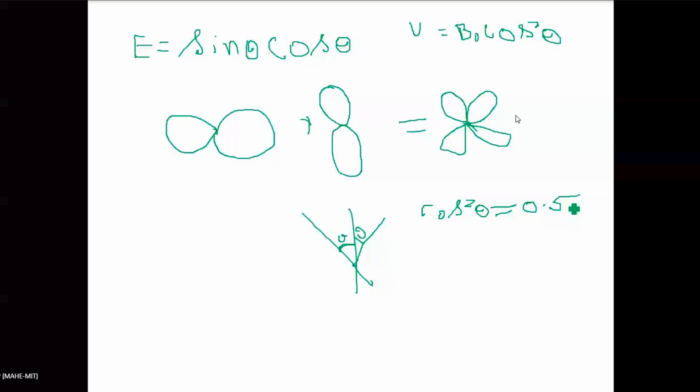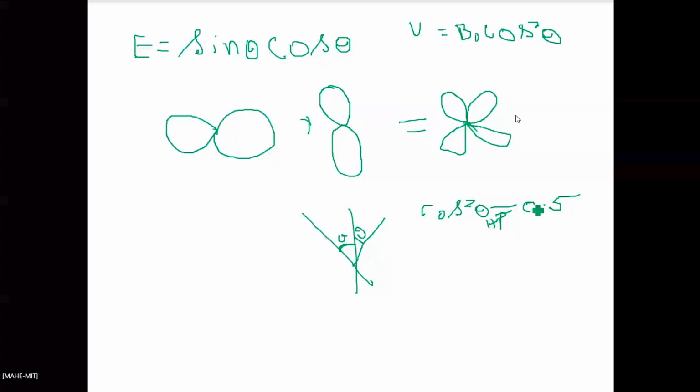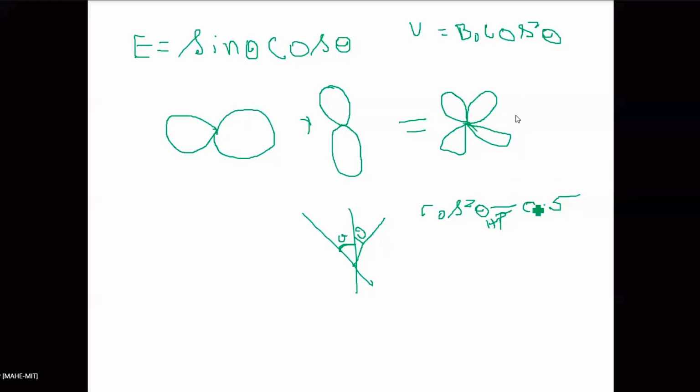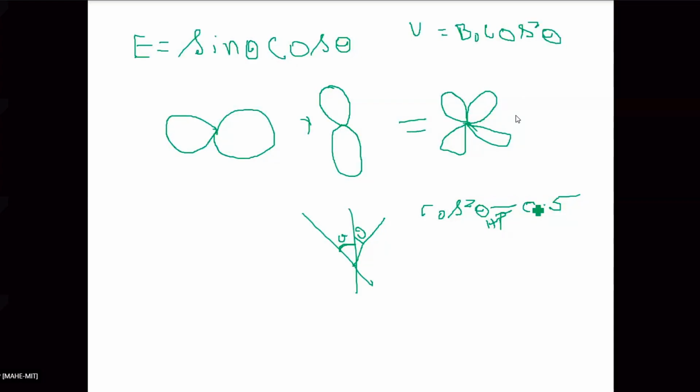So U represents power. I told you, E square or power. If instead of an electric field or amplitude pattern you have a power pattern, with U given as B naught cos squared theta, then the half power point is found from cos squared theta equal to 0.5. Then you find theta hp and the half power beam width. You should not make the mistake of substituting 0.707 for cos squared theta hp. Only when an amplitude pattern is given can you substitute 0.707. When a power pattern is given, it should be equal to 0.5.